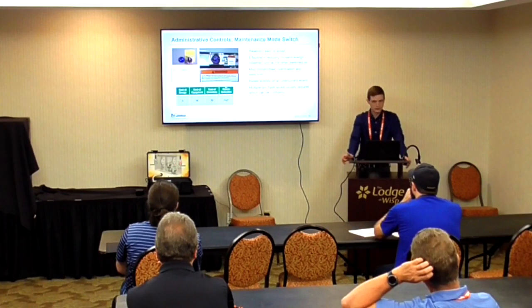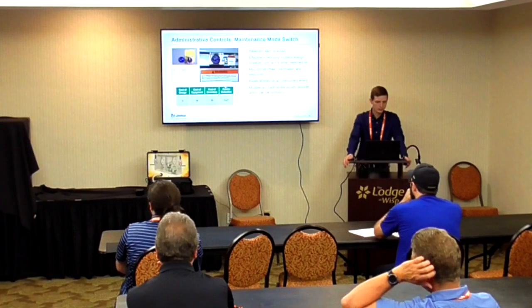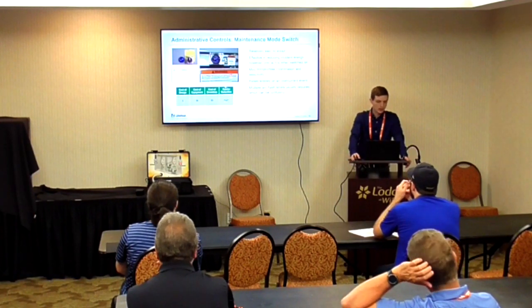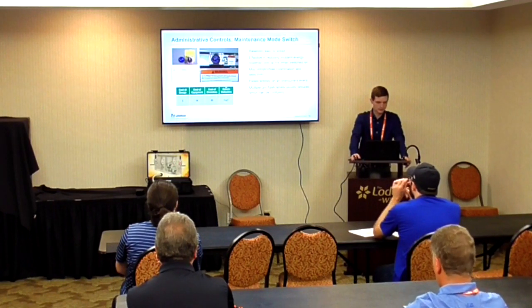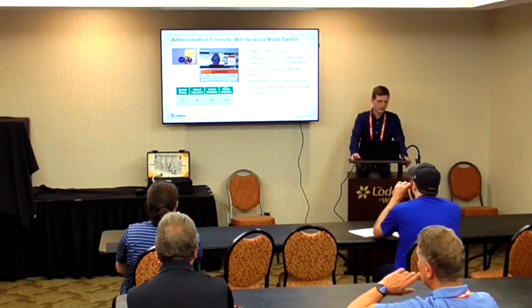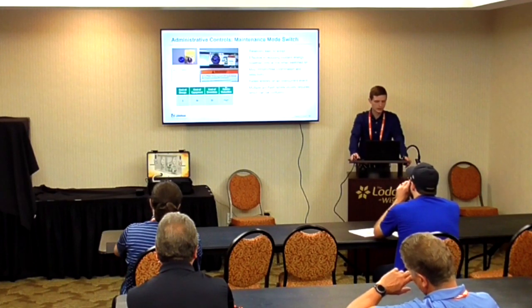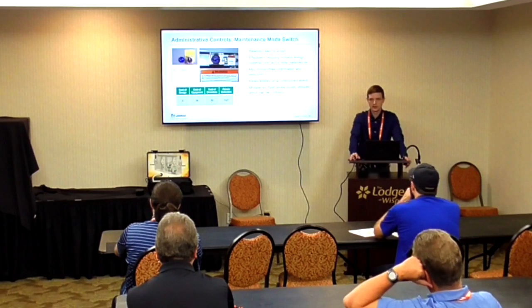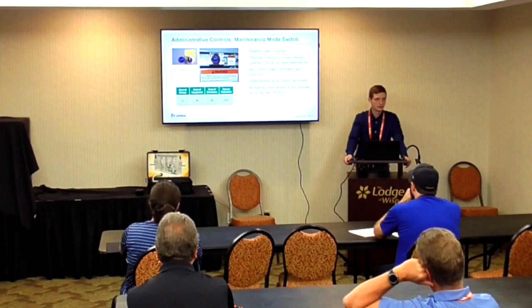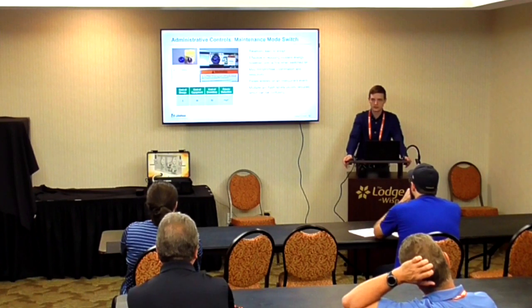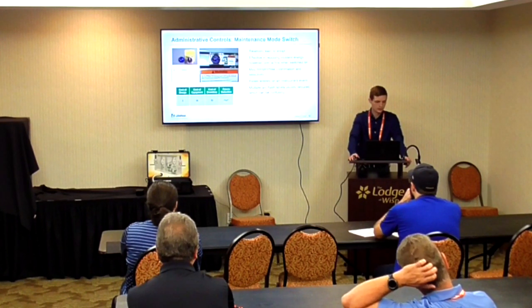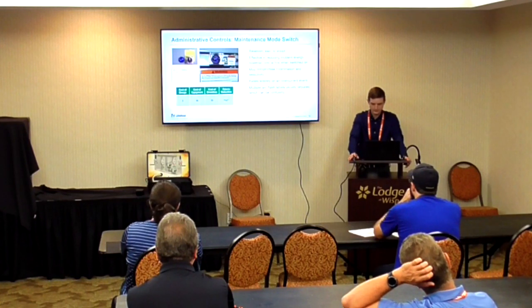Cons, nuisance trips, and the other con here would be in the event that somebody does not read the label, that the label is damaged, or they just forget and they don't trip the switch. So if you've got somebody who's now working in that gear and they do not have that switched over, that means that they now have the full available incident energy. So if you had something that you were otherwise reducing from a 40 cal down to, let's go ahead and say 4 cal or 8 cal, and somebody's just wearing a long sleeve shirt and pants, that's going to be very disastrous in the event that that switch is not used properly.